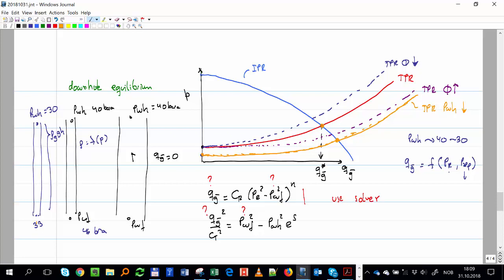Now we're saying the diameter change is clear, right? Yes. The curve is like a flower, has the same point, but it opens. It's these three curves here. Now I'm asking what happens if I keep the same diameter as the red curve, but now I lower the separator pressure. Now it will be 30 instead of 40. Intuitively, what drives the fluid out of the formation is the difference between reservoir pressure and separator pressure, right? If the difference is bigger, I can have more rate.